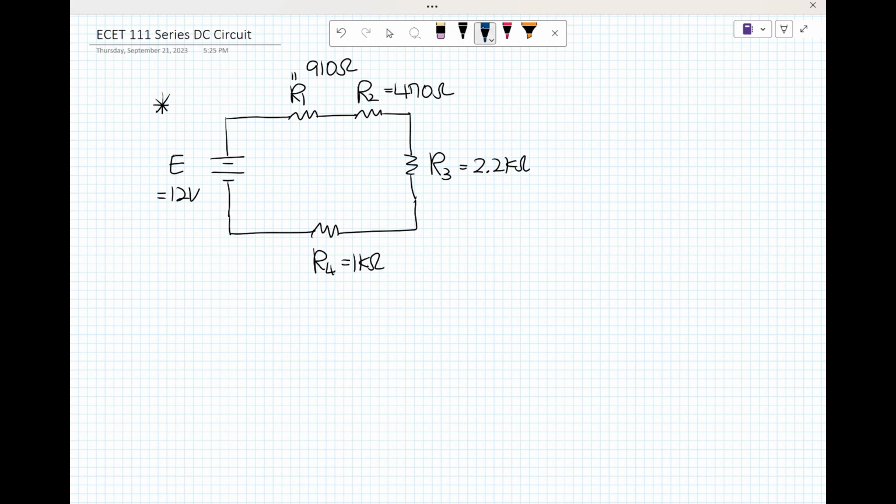For this case, the voltage drop here is plus, minus, because the long bar is plus and the short bar is minus. Plus, minus, voltage drop here. So now, I sub R sub 1 means the current for the resistor, I sub R sub 2 is also the current for resistor 2, and I sub R sub 3 is the current from the high potential to the low potential, passing through resistor 3. I sub R sub 4 is for R sub 4.